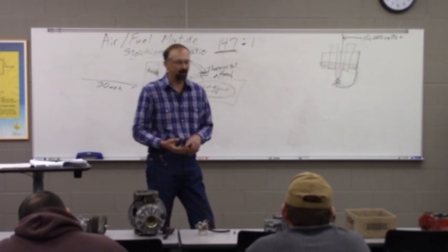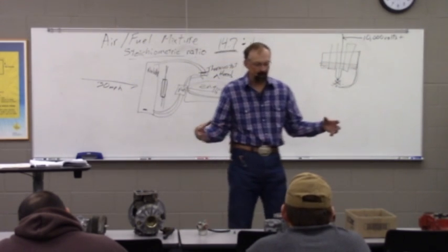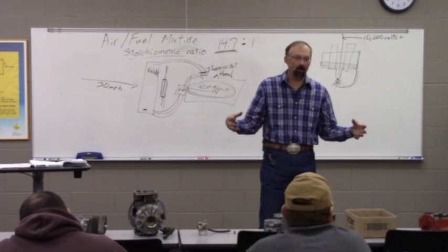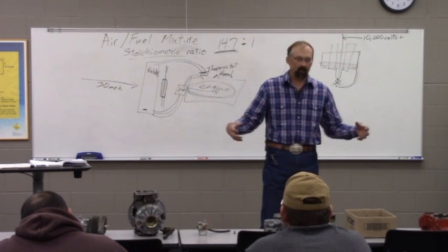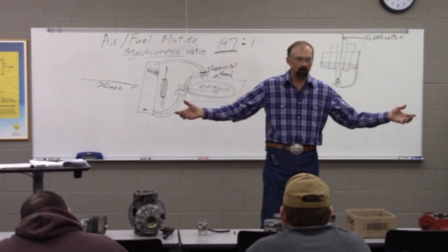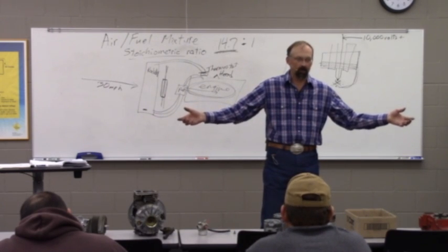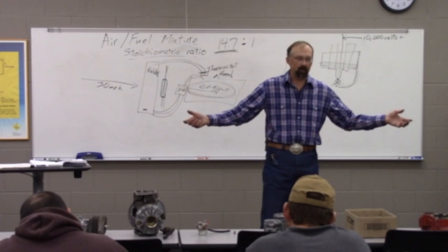Another thing that we've really noticed is in wheel bearings, the ones that are oil bath wheel bearings, which typically the ends of most of your free-floating rear ends are oil lubricated, not grease pack.